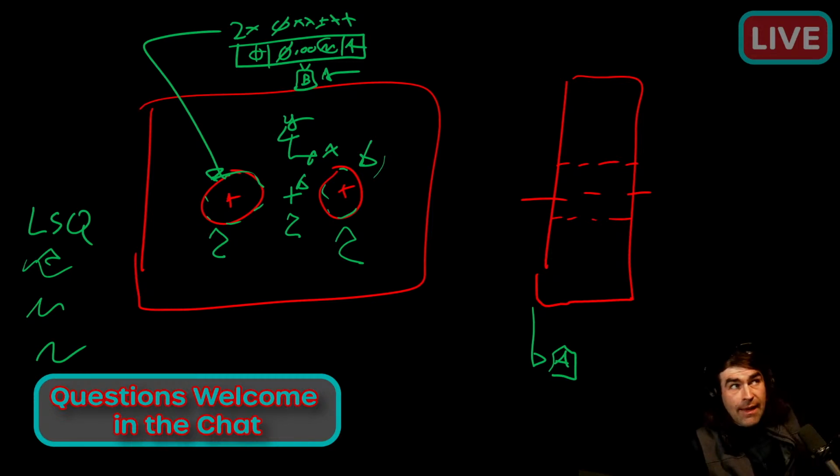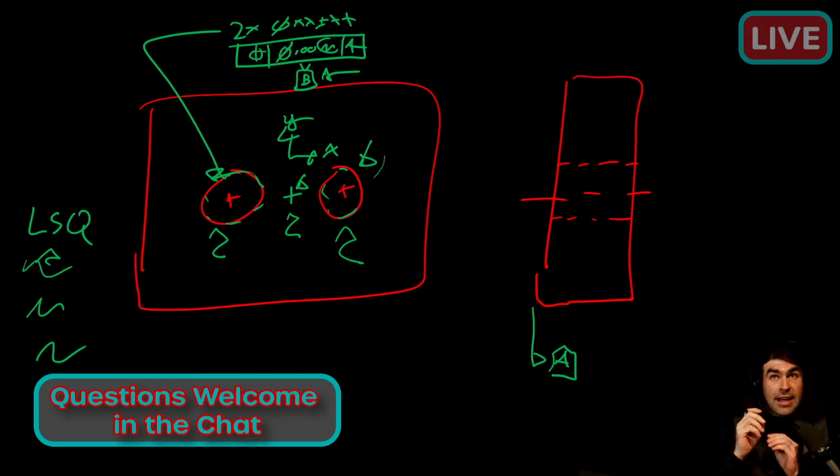I don't see why ASME couldn't do that. So yes, in ISO GPS, you can force fitting algorithms on CMM programmers, which I think is probably good. ASME does specify, but it's not modern enough, whereas ISO GPS, I think they've made it more modern.